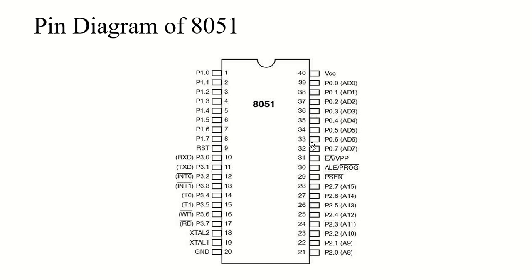Just like port 1 which we just saw, port 2 does not need any pull-up resistor, because it has a pull-up resistor internally. Upon reset, port 2 is configured as an input port.